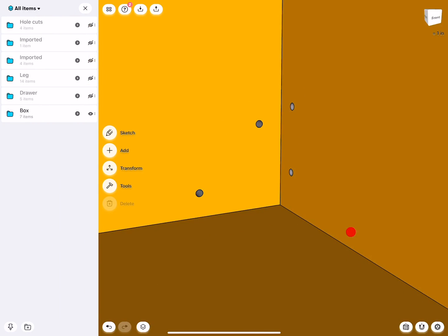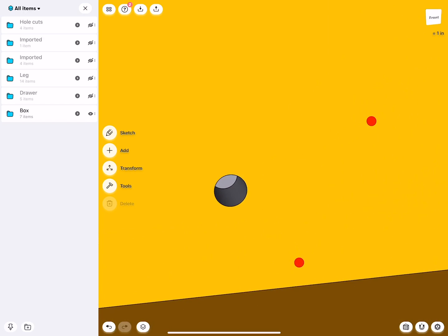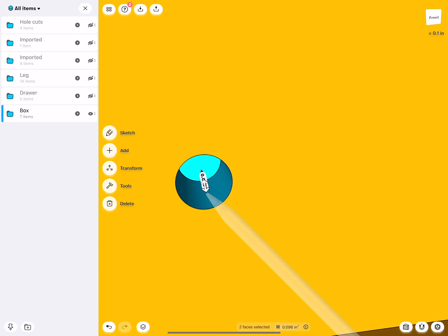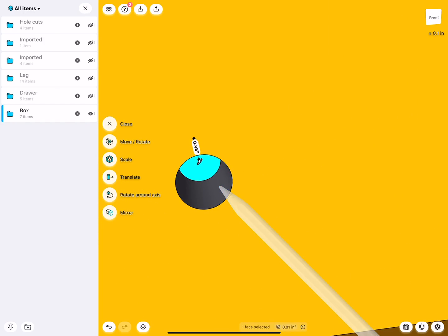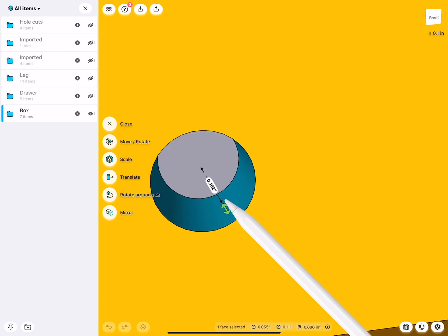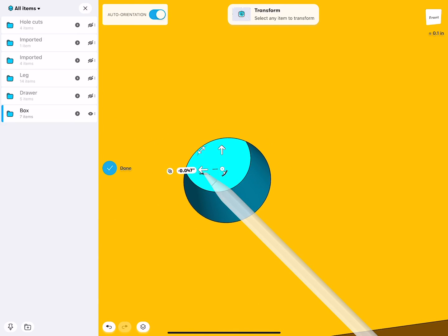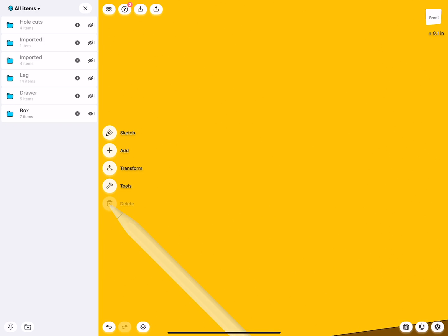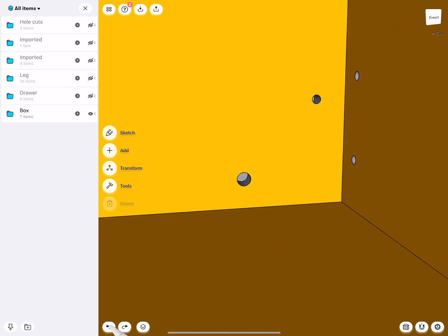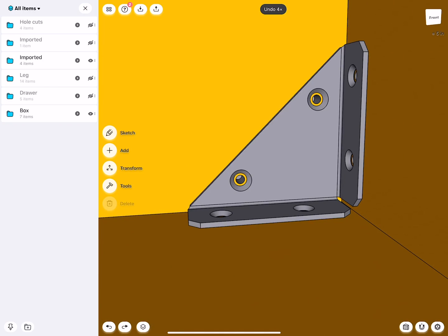There you see that. And these holes can later still be manipulated. We can adjust also the radius as needed. We can move those around, and if we don't want those, we can even delete these holes. So that's a pretty great direct modeling capability of Shaper here.